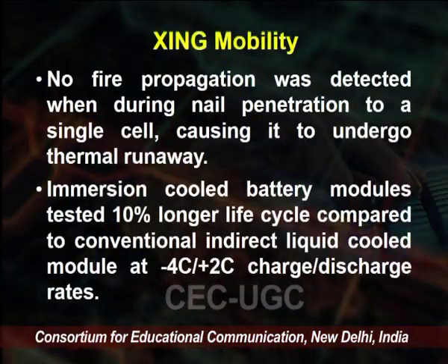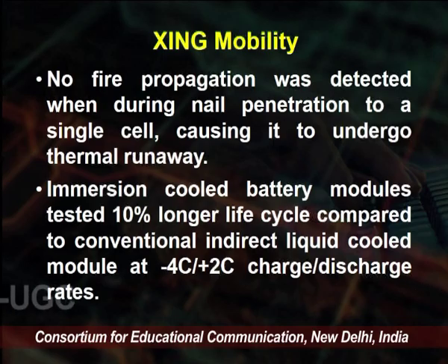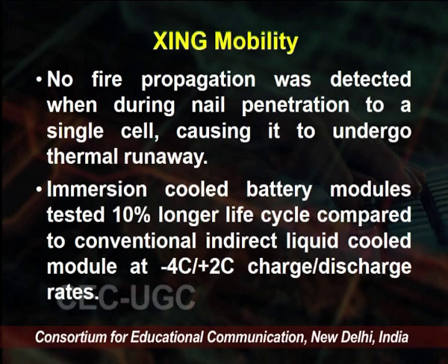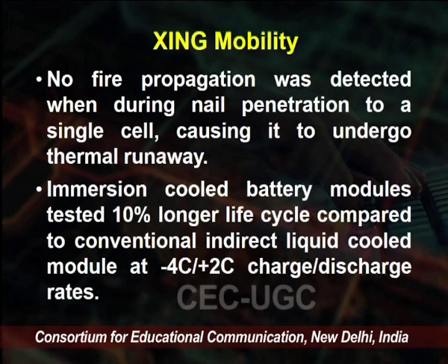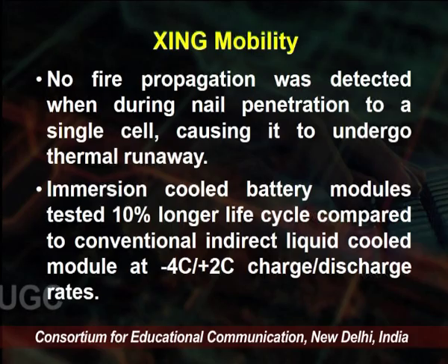No fire propagation was detected during nail penetration of a single cell, causing it to undergo thermal runaway. Moreover, immersion oil cooled battery modules had a 10% longer lifetime compared to the conventional indirect liquid cooled module.